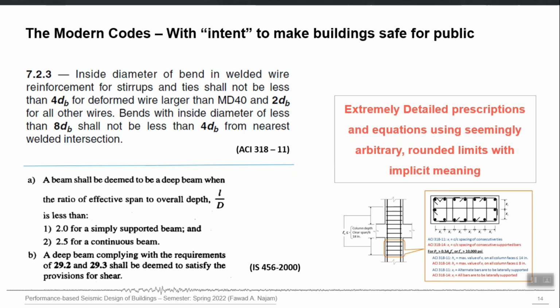So a nonlinear structural model is, you can say, more difficult and more accurate compared to a conventional linear model, and that model doesn't follow Hooke's law. It has the capability to tell the structural analyst that a particular element has already yielded during the analysis, or a particular element is cracked, or whatever damage that building can experience. So that model itself tells what damage is there at the end of the analysis. So you perform such an analysis for that level of earthquake which the client wants you to consider,